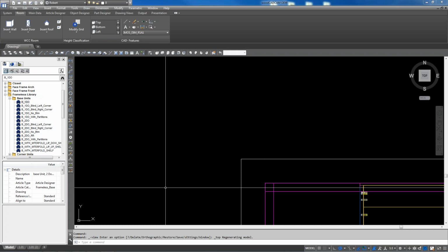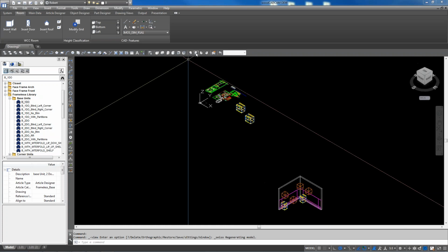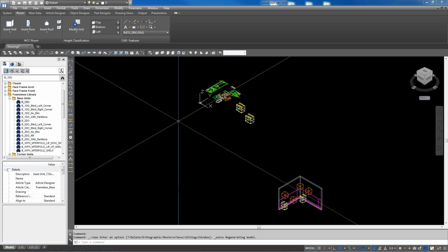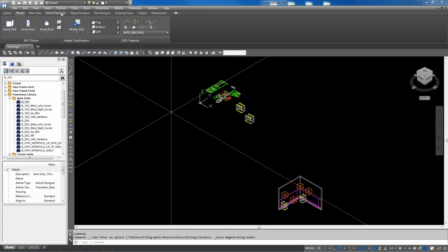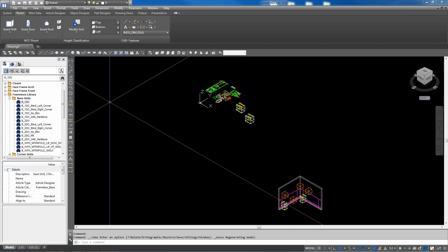Okay. What if we added a 3/4 cleat to the back of the cabinet? Okay, good suggestion. Rudy says, what if we just add the 3/4 cleat that installers use and make it part of the box and then place it on the wall? Yeah, if you did that, then that 3/4 cleat is going to be part of the depth value. So it would cut the rest of your parts down 3/4. Follow me? Yeah.